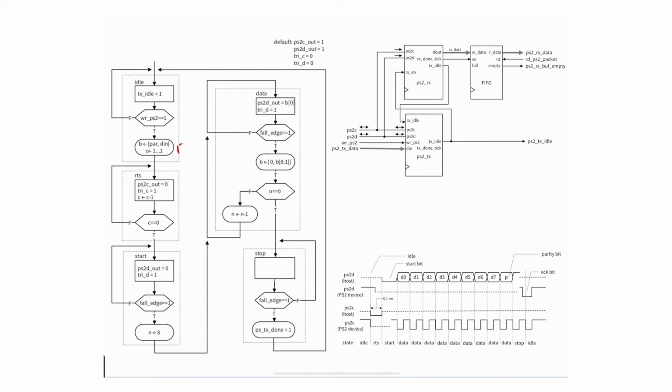Frankly speaking, this will not be 0.1 millisecond or 100 microseconds. This is a 13-bit, basically a bunch of ones. And if you compute it exactly, I believe the wait time that it will actually do is exactly 81.92 microseconds, which is close enough to the 100 microseconds.